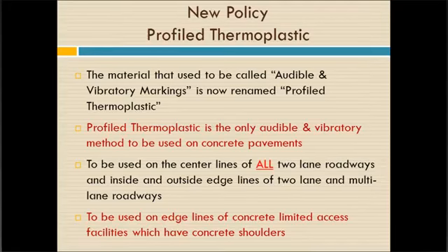So profile thermoplastic: we are only going to use profile thermoplastic as an audible vibratory method on concrete pavements. So if you've got a project out there that's an asphalt pavement where you've been using audible vibratory, you're going to need to change it to rumble striping.